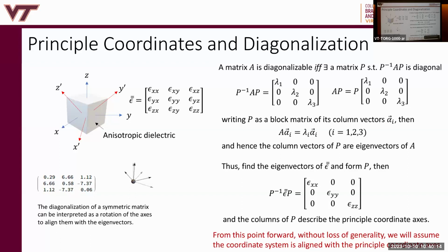So the better you are at Fourier transforms and Fourier series, understanding those, the more power you'll have in solving electromagnetics problems. Remember, we went over that. We looked at the plane wave spectrum, how to expand electromagnetic fields in terms of these exponential bases. And we made the analogy with the Fourier transform. It ended up recasting the radiation integral or the expansion integrals into a Fourier transform.